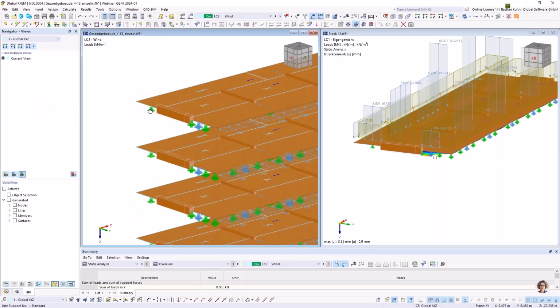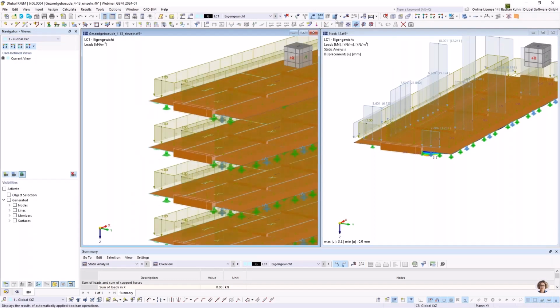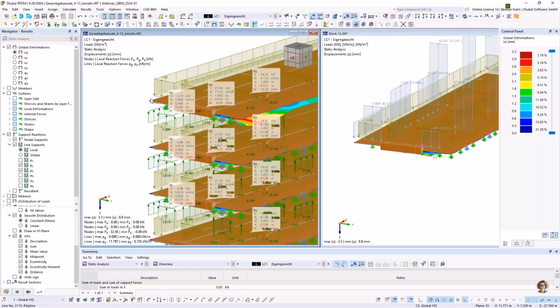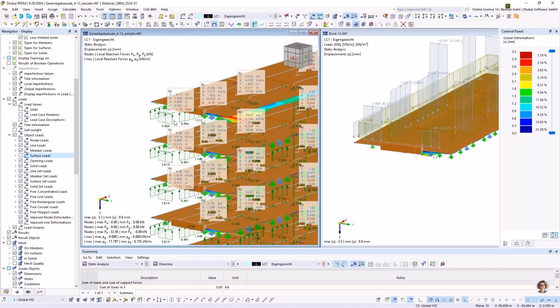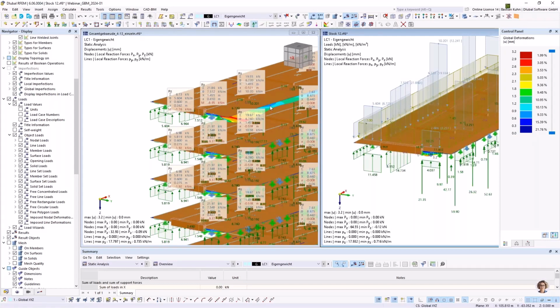And when we look for the results in load case 1 in here, you see that this value we have in here, 5.6 surface loads, is the resultant here. And of course, you also have it on the story 12, 5.8, but as this is not regarding the load transfer from the top, this is already the error that you are making here in this 2D model, because you are not taking the force from story 13 to story 12. This you have to do in this separate position.